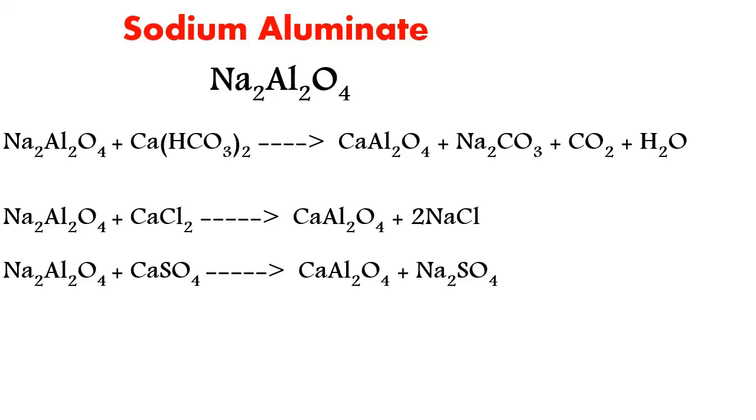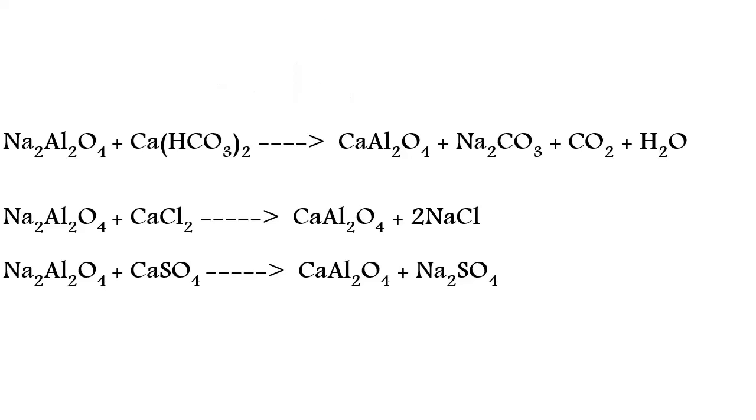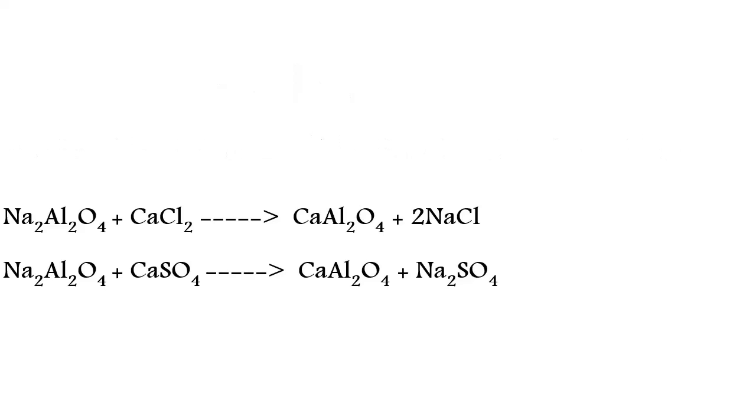But the disadvantage is, this is 1.5 times, meaning 50% more costly than alum. Therefore, we avoid this sodium aluminate. Where we can use this one is boiler feed water. If you want to treat it, you can use it there, because corrosion or incrustation in the boiler due to hardness or due to increase in CO2 is avoided. If we want to reduce that effect, then you can use sodium aluminate as a coagulant.